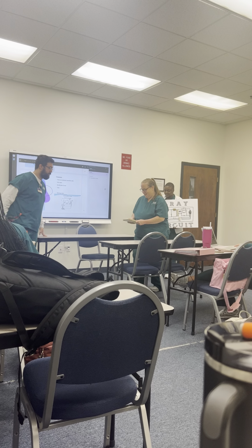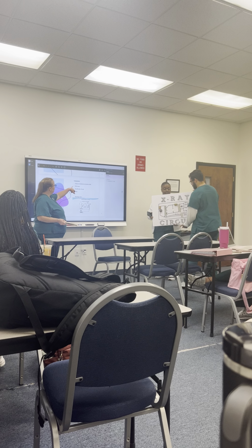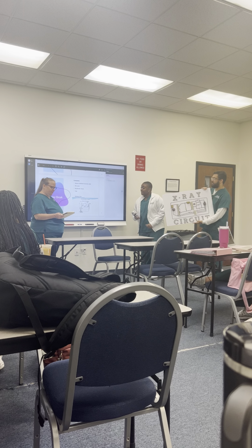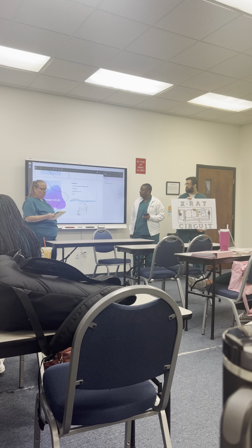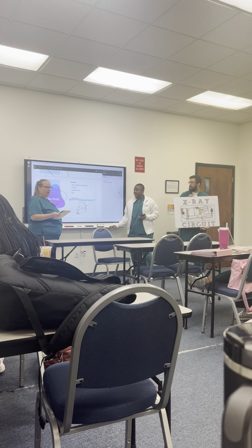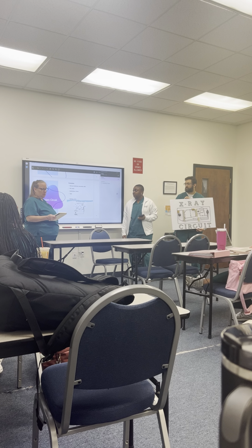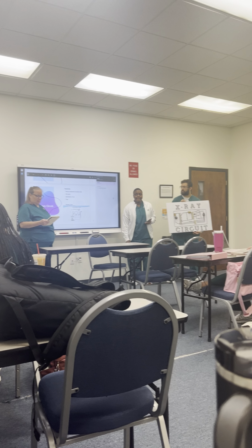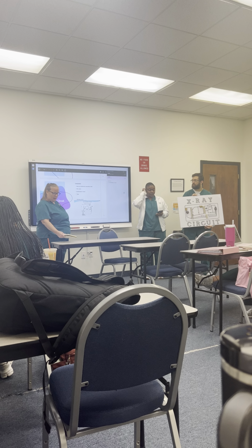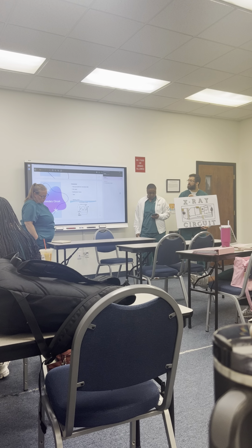So I have the secondary circuit. It consists of the step-up transformer, the mA meter, the rectification circuit, and the tube. The step-up transformer, also known as the high voltage transformer, increases the voltage and lowers the amperage. The primary voltage is measured in volts and the secondary in kilovolts. The primary current is in amperes and secondary in milliamps. So that's the step-up transformer.